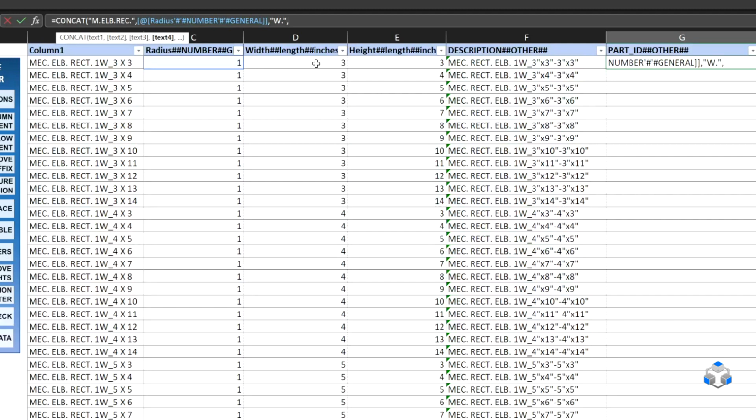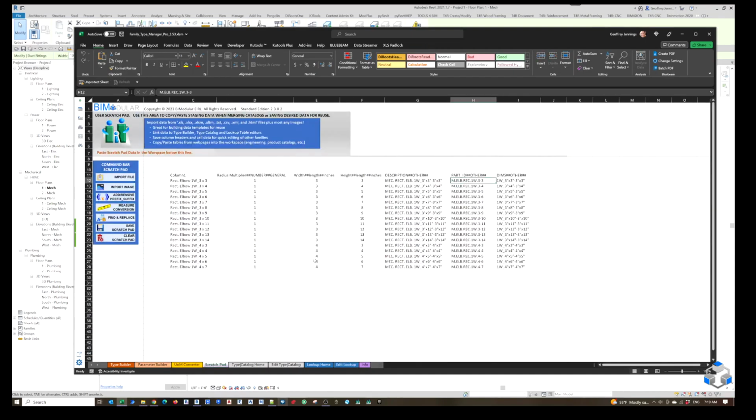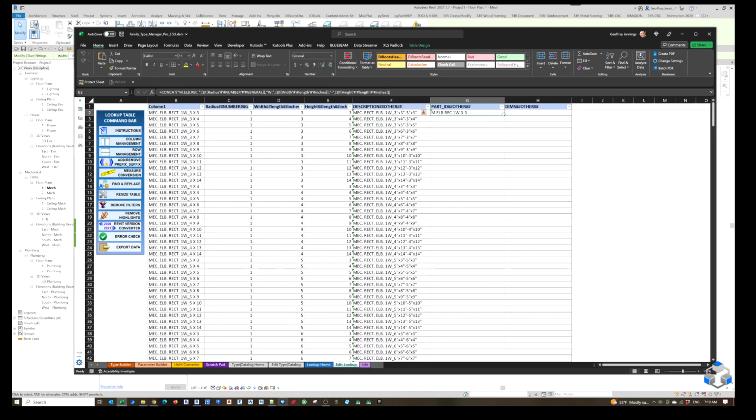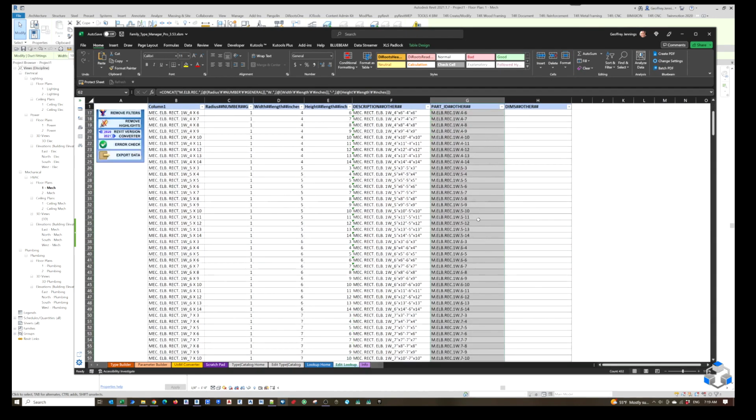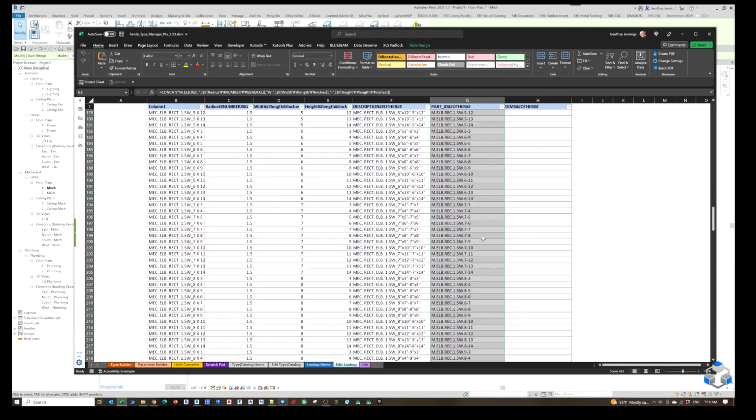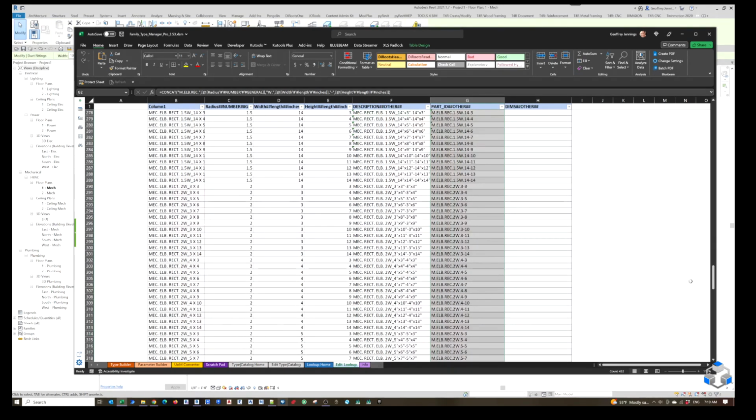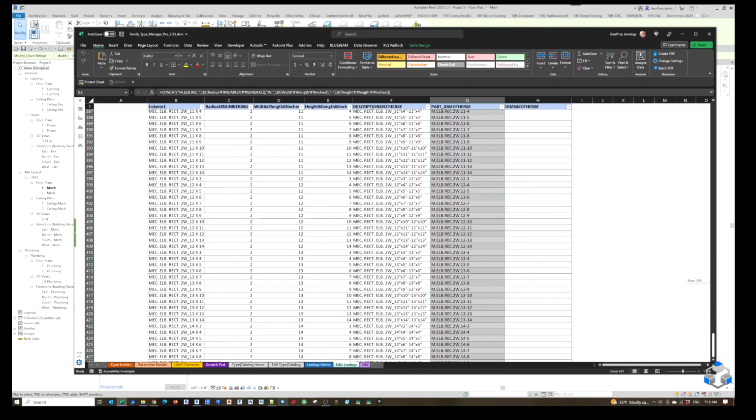So we'll set up here for this value, comma. I believe that's what I was going with here for that information. If I go back to look at my scratch pad, that's correct. So I can now come across here, select this one, and we've now given a unique type ID mark to every single possible Revit family.